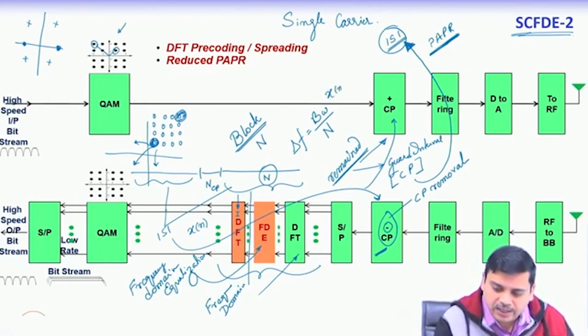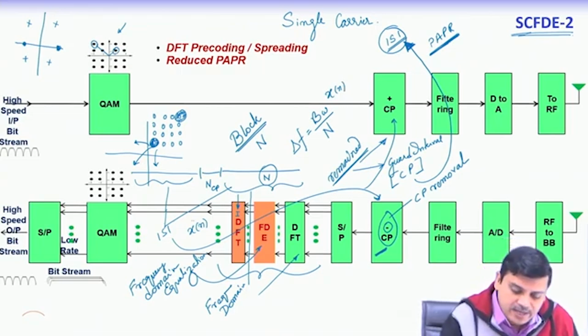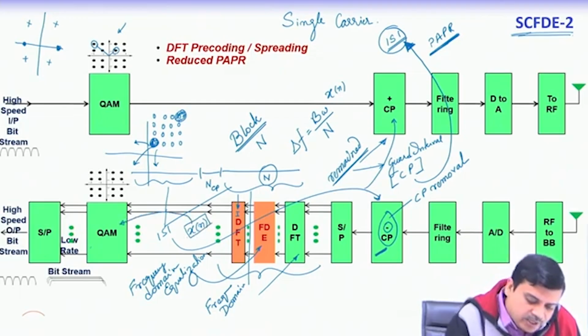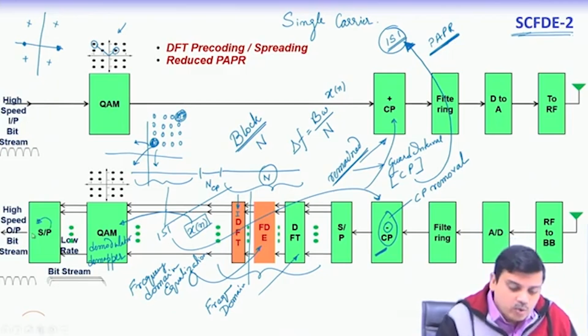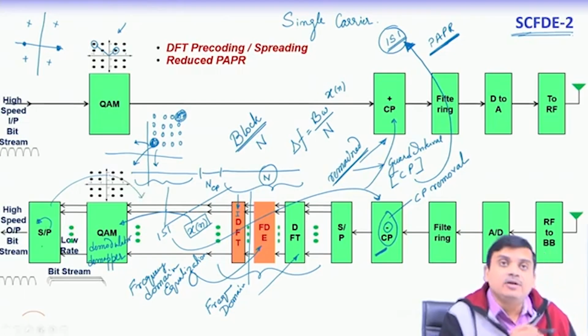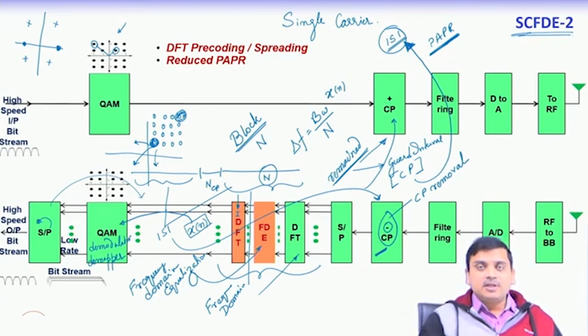What was the signal x n over here? Free from channel, only thing that remains is the noise. So, that one cannot remove, and these can be now sent to the QAM demodulator, or a better word is demapper. We would not use the term demodulator, and then one can think of serial to parallel to serial conversion. This is parallel to serial conversion, or one can think of bringing this module earlier and then doing with one single QAM demapper. So, this is an extreme case of single carrier FDMA, and one can reduce the PAPR like anything.